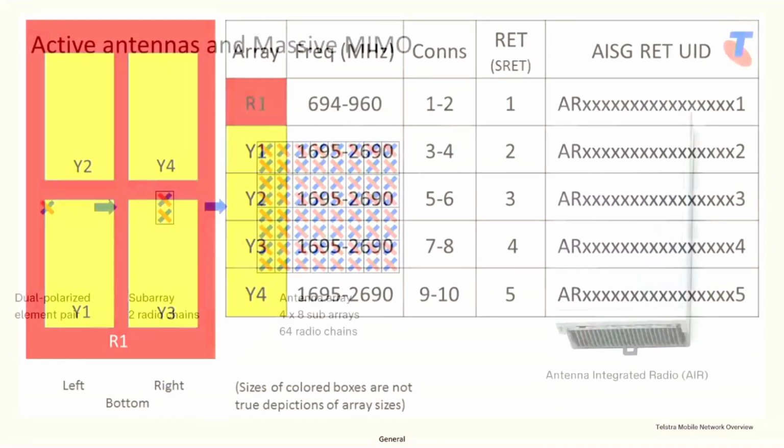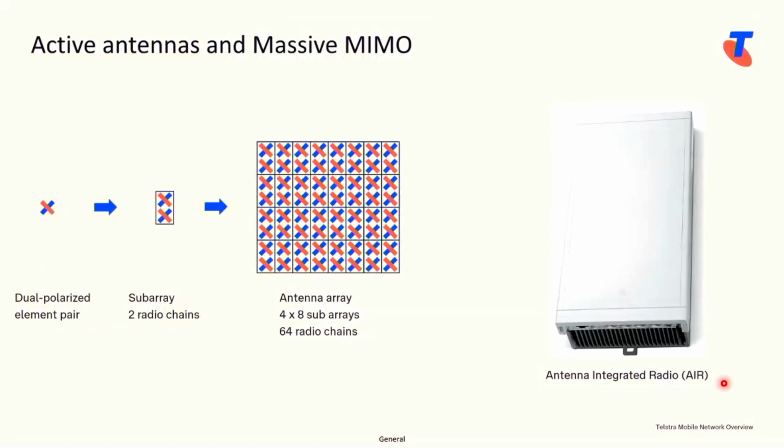So that's a passive antenna, and then this is an active antenna. We call it a massive MIMO antenna. Have you heard about MIMO, massive MIMO? Yeah. So that one that's up there is pretty much like this. There's 128 antenna elements in there. They're dual polarized, cross-polar design.